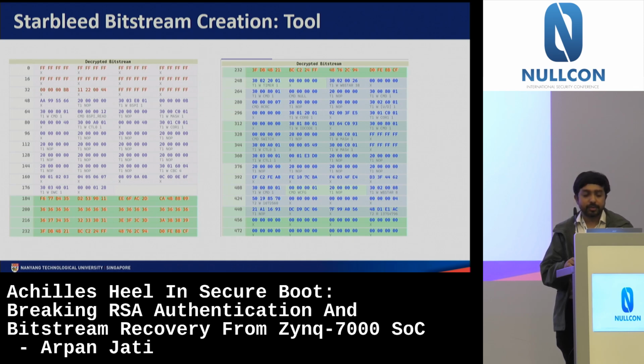In this case, we had to do two faults, and using the two faults, we are able to create a bitstream which is actually loaded by the Xilinx FPGA and it works correctly. The rest of the things are not required, so it becomes a few kilobytes. The thing that you are seeing here is the only part that is actually required. Before and after, we just remove.